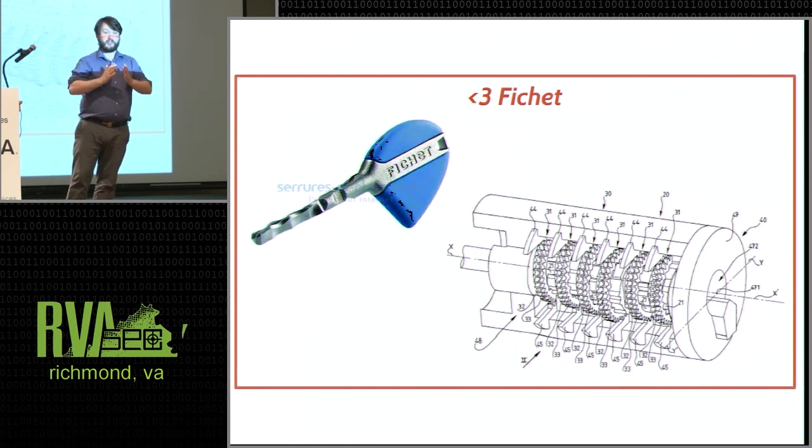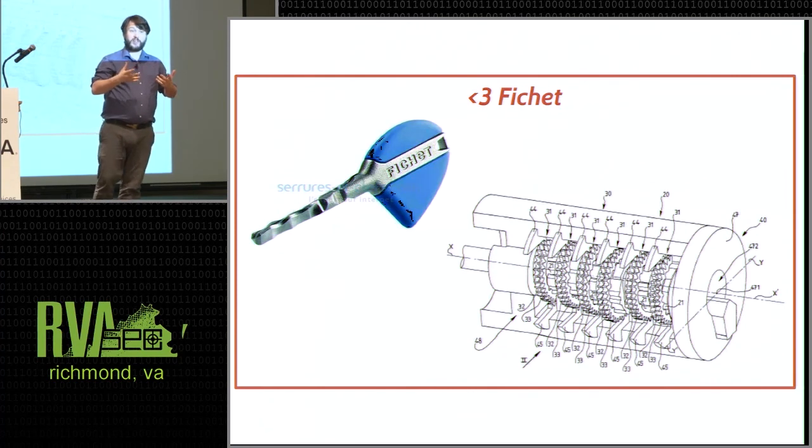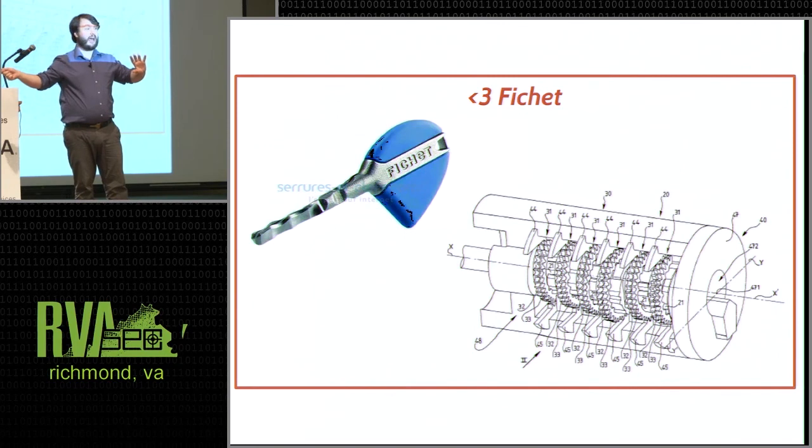The way they build the difference in is that they slide the key into the lock and then put the sidebar wafers on, so that whatever position all of the gears are in, with the key inserted, is the open position of the lock. They then slap the sidebars in, remove the key for the first time, and everything is scrambled to the now unlocked position. And as a result of that assembly process, they were able to patent protect their key, making an end run around the French patent office.